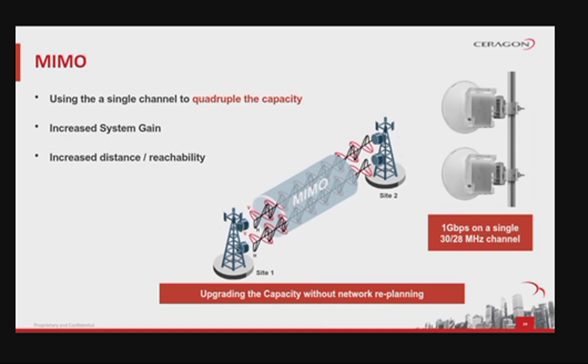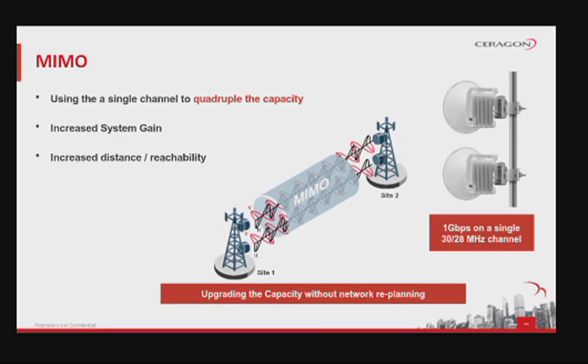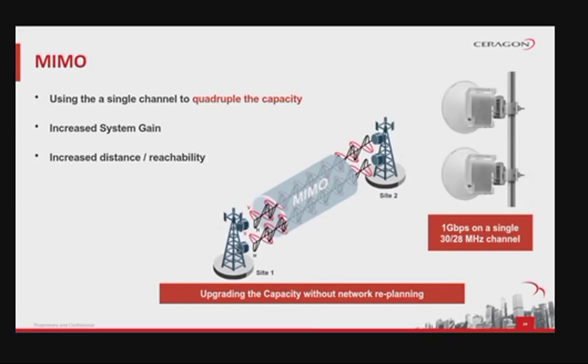The figure in this slide illustrates a 4x4 line-of-sight MIMO direct mount configuration. The 4x4 line-of-sight MIMO utilizes two IP-20C units. Each unit uses dual polarization, with all four radio channels using the same frequency. Each unit is connected to an antenna using an OMT mediation device.